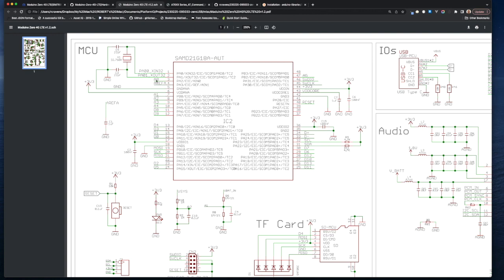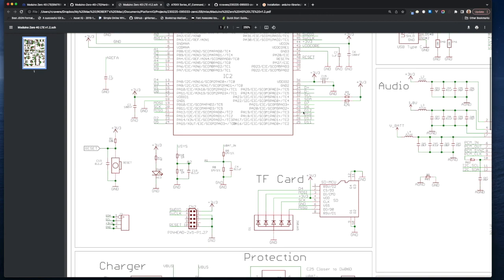And in particular, you can see pins labeled A0, A1, A2, A3, A4, and then here's an A5 pin on this side. Those are 6 analog input pins, 0 through 5. And on those 6 pins, there are analog to digital converters. And so you could measure the voltage on those pins using one of those A to D converters.